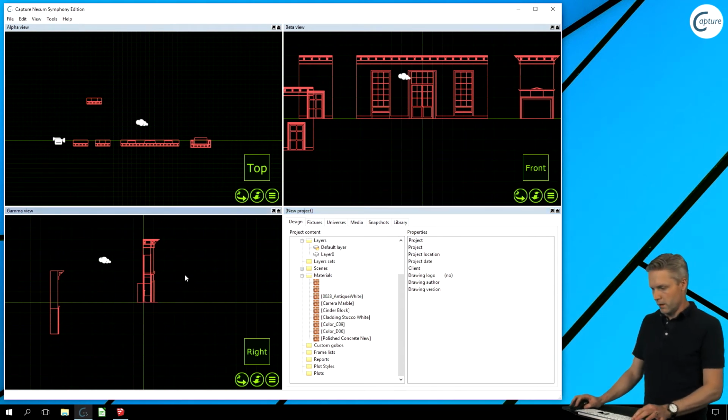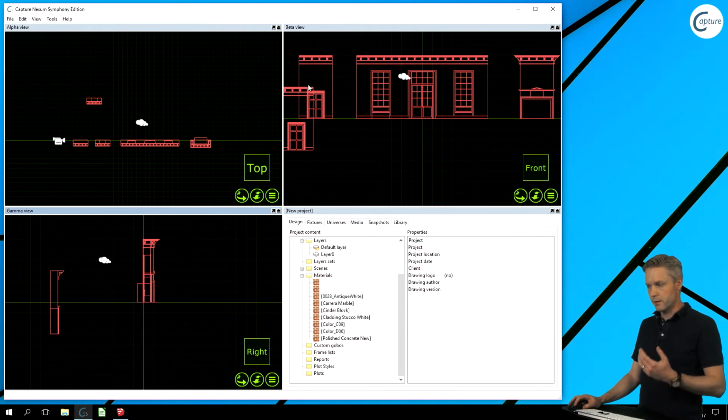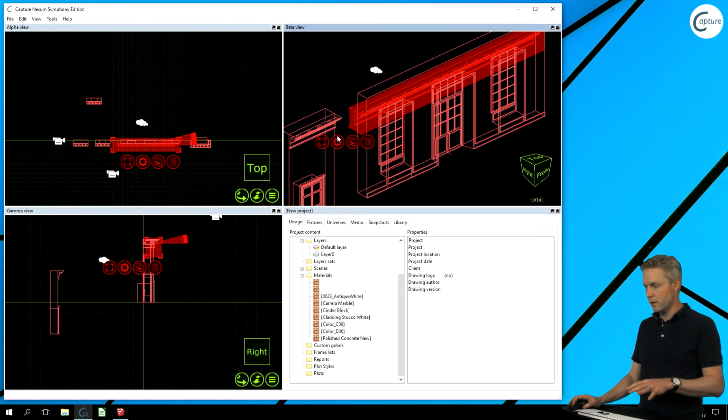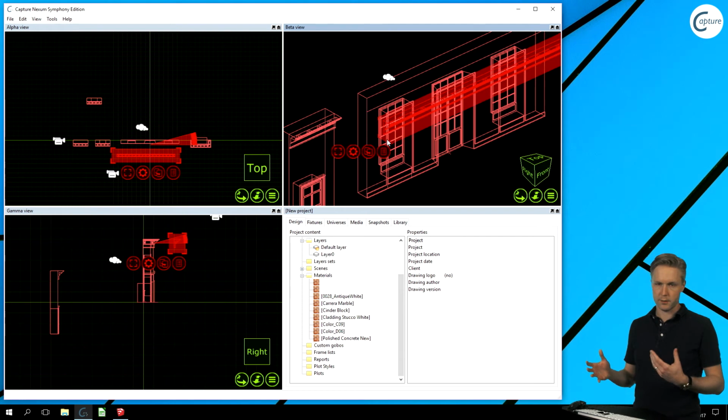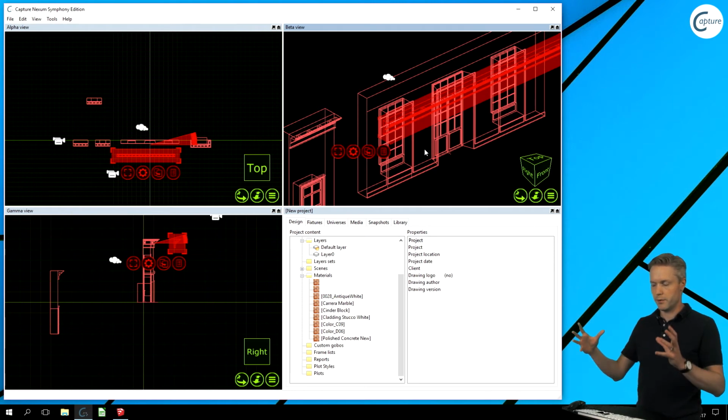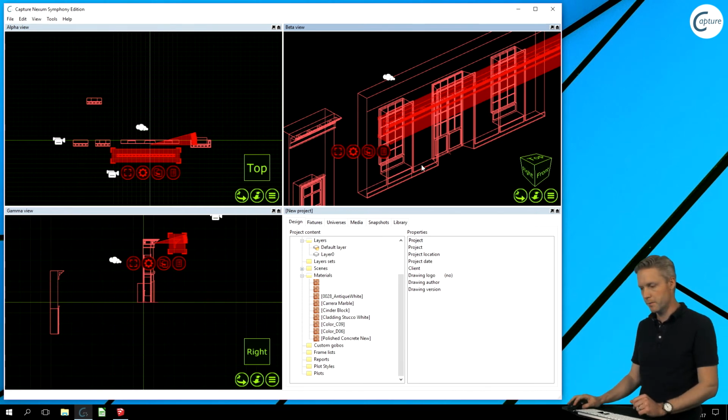All right. Finally, it is worth noting that the way the objects are imported in terms of which subparts are selectable and movable, this depends a lot on how the file was drawn in the original program. If everything is in the same layer, uses the same material, then you will be importing one giant block basically, which you will not be able to split in any way.